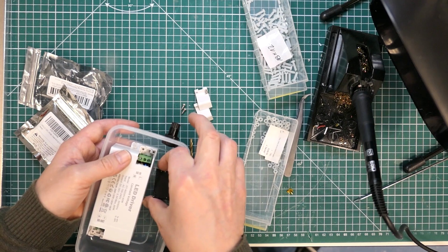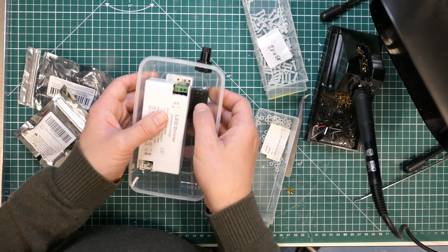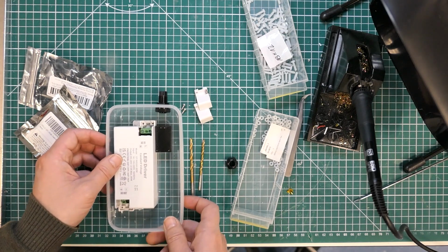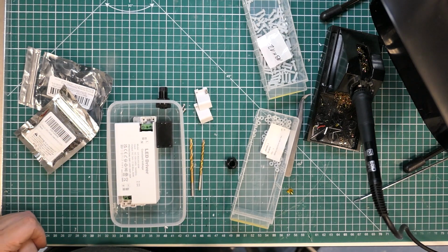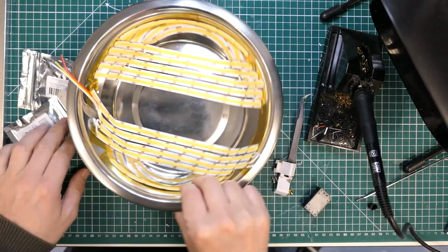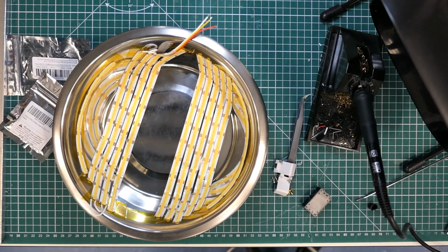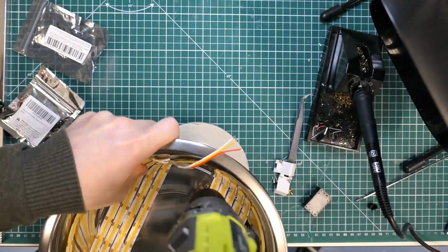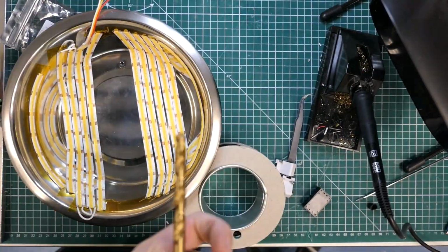So this is just a replacement of the regulator I showed on the schematic, and it actually adds complication and danger to the circuit. So do as I say and not as I do here. Don't use one of these expensive little modules. Use a perfectly adequate little 5-volt regulator to give the 5 volts needed for the ESP. You just plug the 24-volt input into its input side and take the 5 volts from its output side.